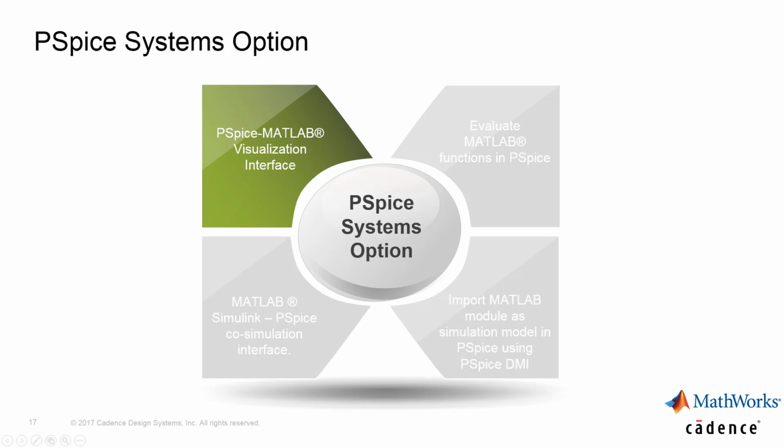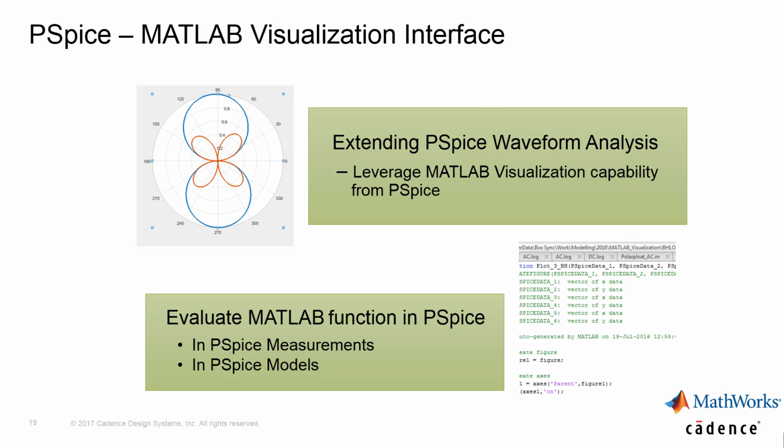So let's talk about some of these in detail. This slide shows you how you can leverage the MATLAB visualization capability from PSpice. In other words, you can import a PSpice waveform data into MATLAB and visualize the same data in the MATLAB environment in a different form like a polar plot. You can also evaluate the comprehensive MATLAB functions in PSpice measurements or the PSpice models.